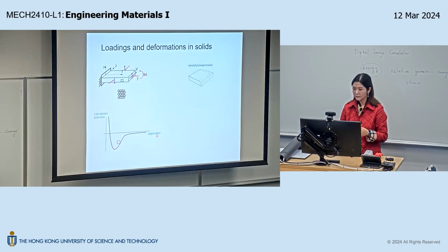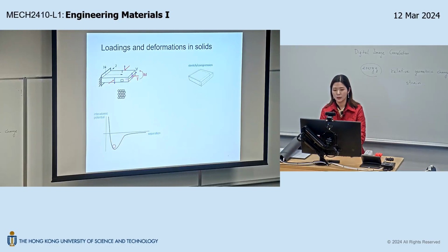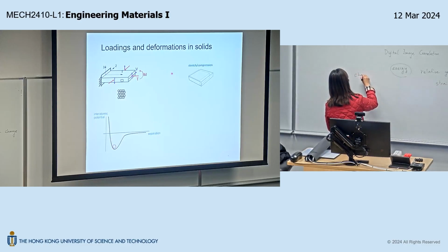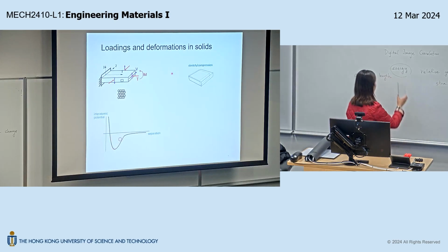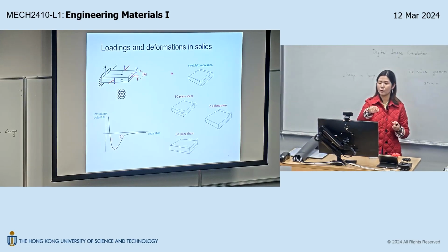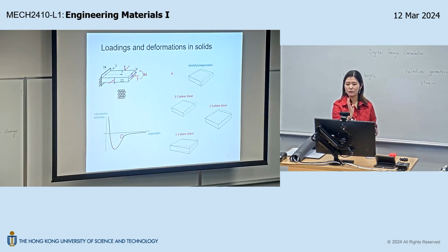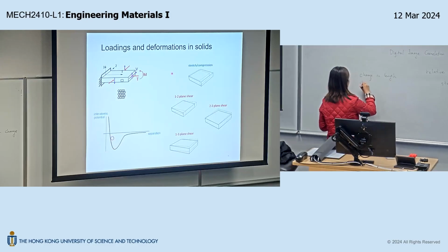Okay. So if we have normal force like the red force, in your mind, you have to have this kind of mapping, okay? That maps the pure stretch and pure compression. That's the change in length, right? I think your solid mechanics instructor will tell you normal stretch changes length. That corresponds to the red force here. And if you have the purple force, right? That's V, we call it shear force. Okay? The shear force gives you change in angle.